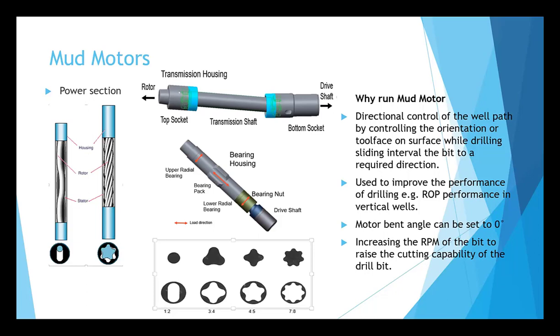Some of the issues with a positive displacement motor are that you cannot have the full weight down the string. You can have string compression and friction. Sometimes you can have an issue of the string getting stuck at the bottom. Also you can have hole cleaning issues, because the cuttings cannot just come out. So these are some of the issues we have. Otherwise, we can get good help for directional drilling with mud motors.